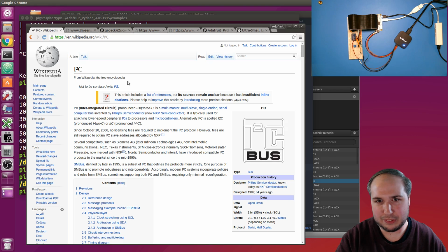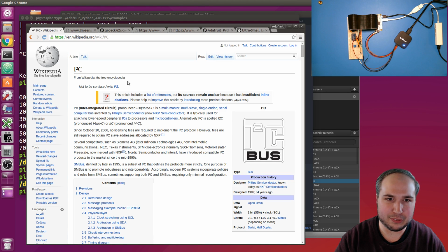In most cases, a lot of devices that we use are register based, and so we can use the smbus kind of libraries and protocol. But there are some devices, like I was actually just dealing with a little humidity sensor, the SHT31, that doesn't use registers. We'll look at that at the end here when I look at the raw way to interact with I2C devices. But it's just something to be aware of, that you might see smbus, and whenever you see that, you really just need to think, okay, that's I2C, but a little subset of I2C.